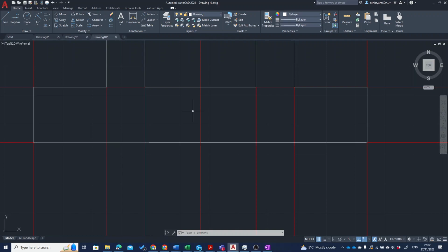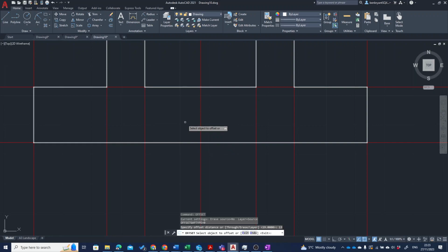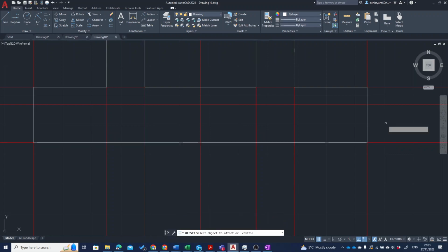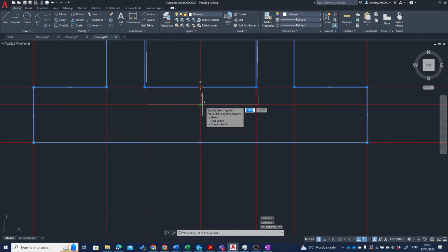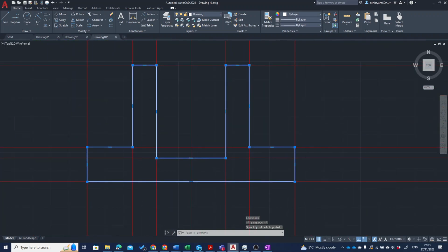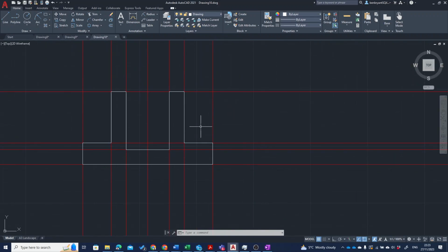What some people do is take a line and just offset it for 13, so I could use my baseline, map it up. However, I've just made a polyline, so I have to use my construction line to reference that up. Because I've made a polyline rather than a single line, I can click on this bit, drop it down, click on my new element, close. I haven't got to do any trimming. If you did that with the line tool, you'd have to extend all three lines down, which isn't a problem. It's just another way you can quickly speed up editing your drawings if everything's properly constructed.